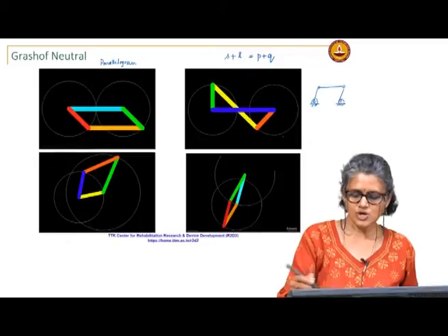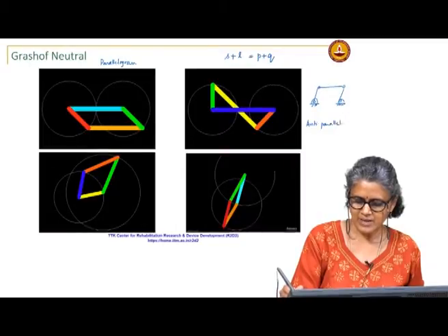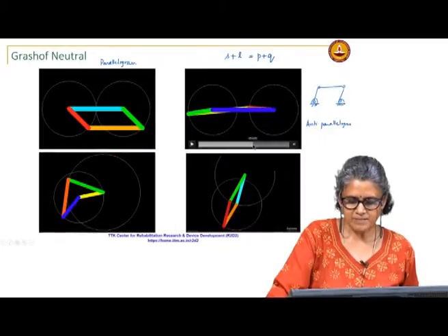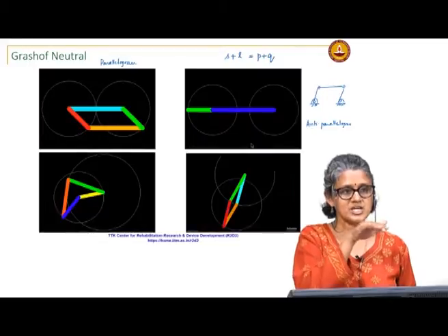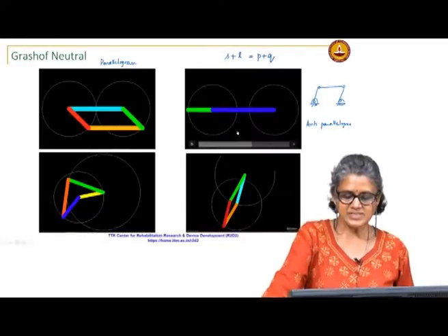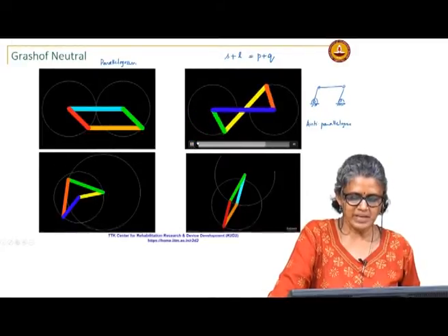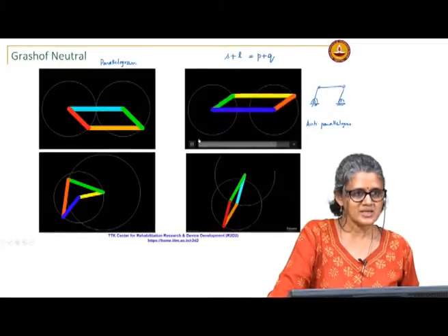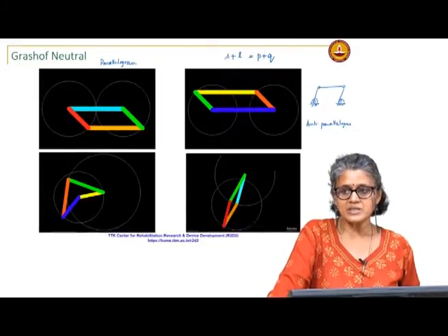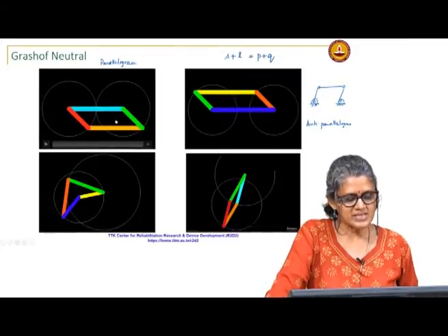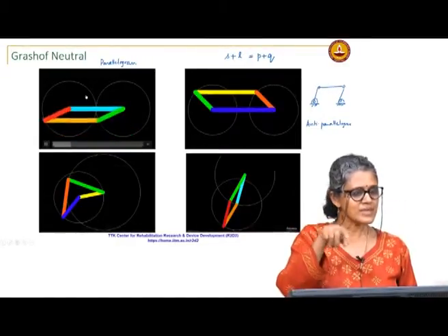and this one where it is crossed like this is called the anti-parallelogram form. It is the same links in the anti-parallelogram form. So, you can see here when the links line up like that, that is called a change point, and there is some unpredictability associated with that change point. You started off with an anti-parallelogram mechanism, and you can see here it switched to a parallelogram mechanism. So, your output becomes unpredictable. In this case, we did not see this because of the inertia of the links; if the inertia of the links is able to carry it through, then you do not have a problem.